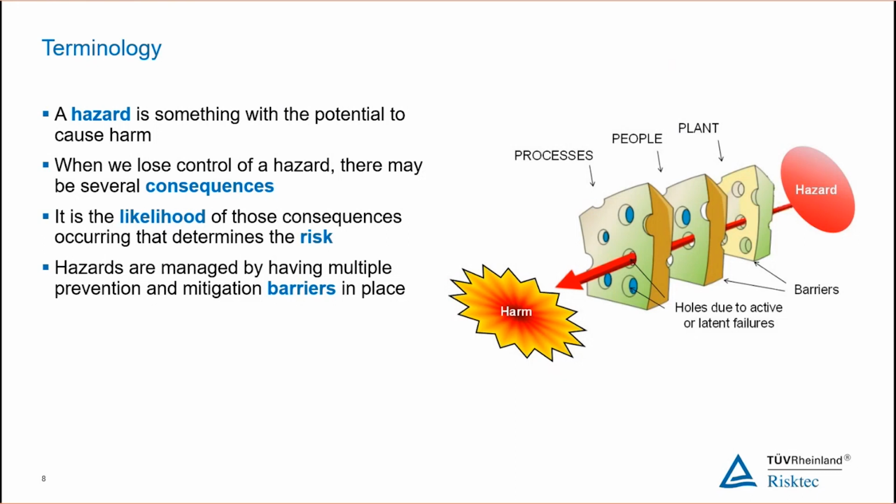Now, this leads into a very important point: this is why we investigate near misses, because near misses will tell us if, say, the first barrier in our layer of defences has failed. And so if we have a near miss, then we can investigate that near miss, and that would tell us, yes, we can repair that barrier before something passes through it and possibly challenges the integrity of the second barrier. But these holes, they might exist for a number of possible reasons.